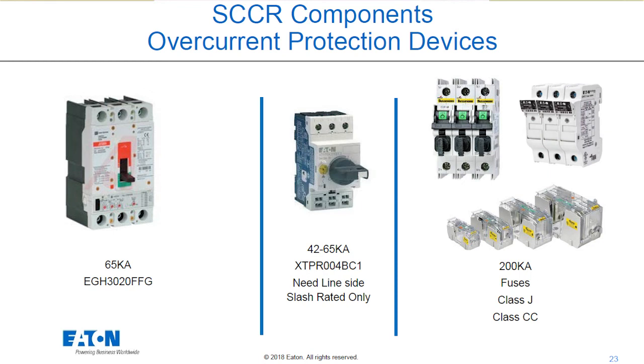So you could put one set of fuses and a whole set of your manual motor protectors underneath of it, and that actually turns all of those into a straight rated, or simply not using that and replacing it with fuses, depending on what would work better. But the way that you can turn it into a fully rated device is by fusing it.